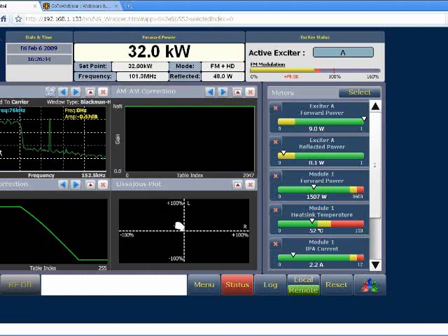Okay. And you can see the left plus right and the pilot and the suppressed 38 with the left minus right in the stereo. Double sideband suppressed stereo. And you actually see an SCA carrier. Now, I noticed this thing has a marker on it that I can use, so I'm going to move that marker across and see what my levels are. It's just like an instrumentation spectrum analyzer. So there's my 19 kilohertz pilot.